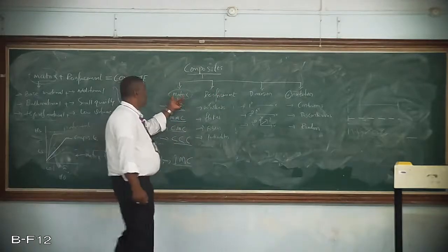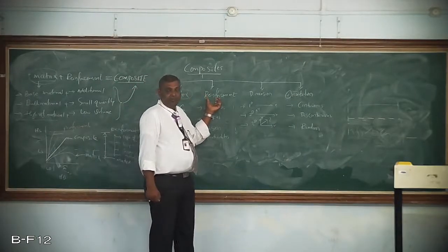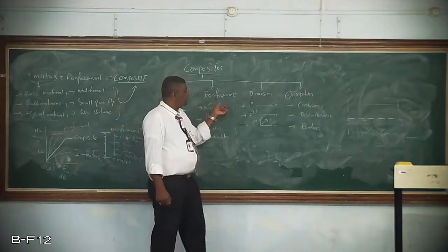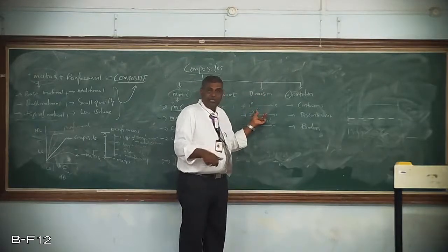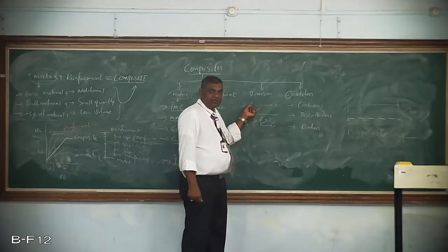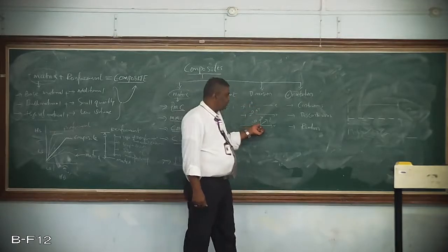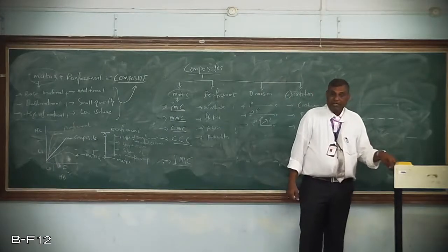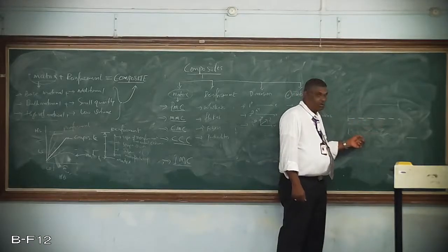That is, what matrix material you are going to use, what is the type of reinforcement you are going to use, and what shape you are going to use, then how these reinforcement are aligned in the base matrix or the base metal or in the bulk material. So whether it is in the order of one dimension, two dimension and three dimension. So next is continuous, whether that alignment of reinforcement in matrix is continuous, discontinuous or random.